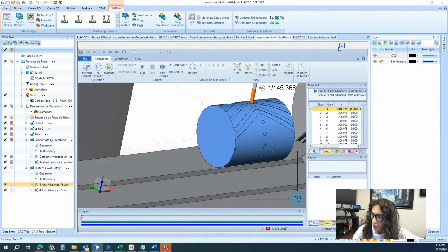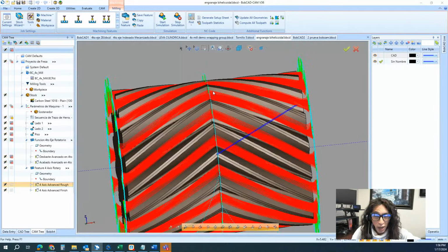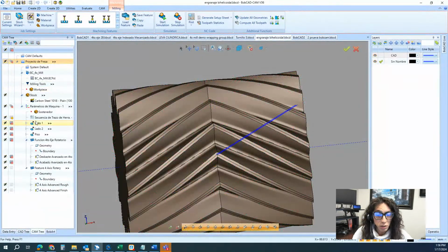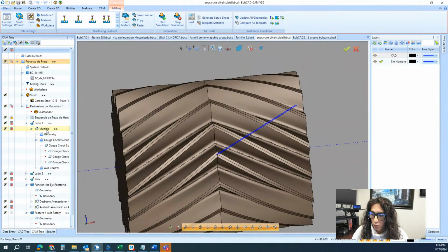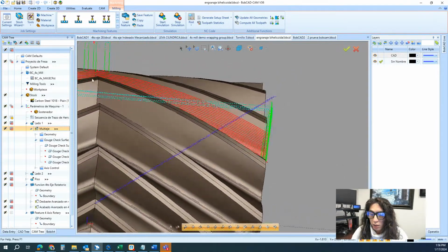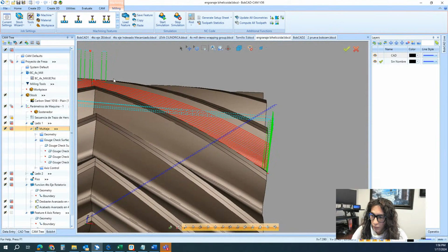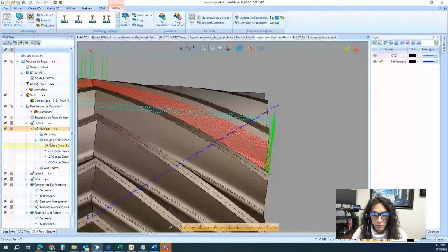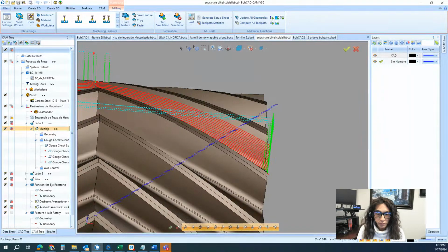The way I will do it, to have more control of what the toolpath is gonna do, I will use the surface toolpaths. So I programmed this part two ways. The other way I did it is by doing this, utilizing the surface toolpath. With the surface toolpath, you can increase the distance, so the distance comes from the outside, and it doesn't break and plunge your tool. So I will use this multi-axis to have a little bit more of a gouge control situation.